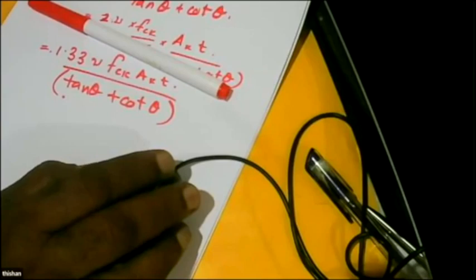Generally, a rigid arm should be made of beams. If you look at textbooks, what is recommended to form a rigid arm is always a beam. You cannot find anywhere in a textbook where they say, use a shell element and create a rigid arm. Is that clear? Yes. So always, if you look at the standard textbooks, they recommend using a beam to create a rigid arm.